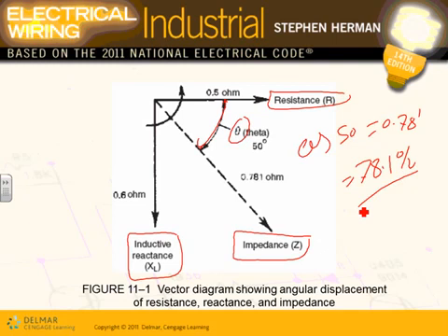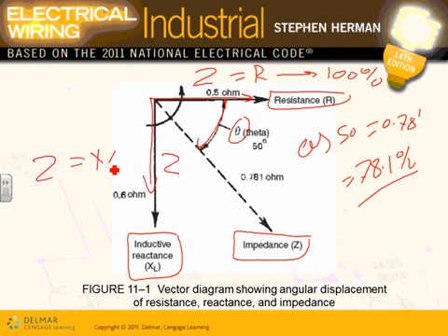The best power factor, guys, is when Z sits like here. Here's a Z. So basically, Z equals R. That's equivalent to 100% power factor. When Z sits here, here's my Z, which is Z equals XL. That will be your 0% power factor, theoretically. Do you guys see that? The 0% power factor versus 100% power factor.